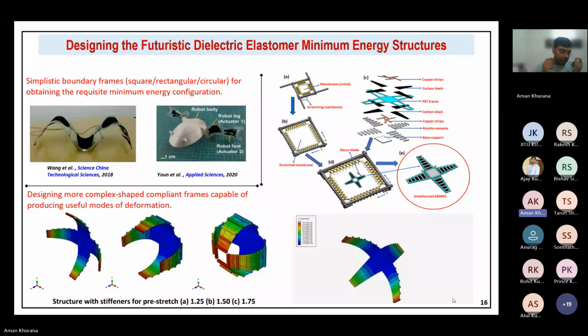Second thing, in the case of the acrylic elastomer that we have used here, we can have a stress relaxation period. So you see here, initially we have the pre-stretching of this dielectric membrane. After pre-stretching, we don't directly put all this stuff on. We wait for a 24-hour stress relaxation, and after getting stress relaxation, then we incorporate all this. That is one way of overcoming it. The second way is we apply the voltage in very small steps, like 50 volts per second. That is the other way to mitigate this viscoelastic effect.